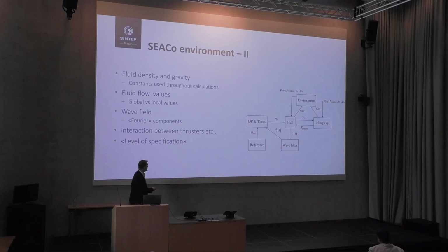When we started this, we had a very abstract look at what we use when we do marine simulations and try to couple separate models from different domains or different suppliers. Basically, both equations use the acceleration of gravity and some densities, so they have to be the same. You would be surprised how much 1000 versus 1025 crops up in computer code, for the density of water.